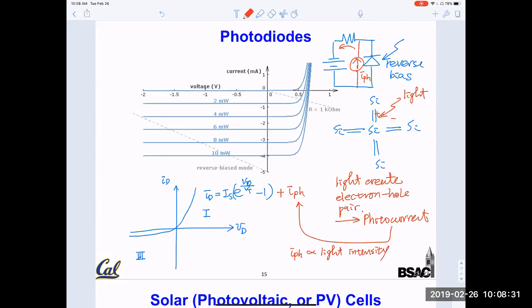And what happened here, if you add a current component, and the current flows in the reverse bias direction, you are basically linearly shifting the IV curve. So with light, this curve will be shifting like this, all right? It's like a uniform shift, okay? All these arrows are equal, and these arrows are exactly photocurrent. If you increase your light intensity further, if you have more current, it just shifts further down.